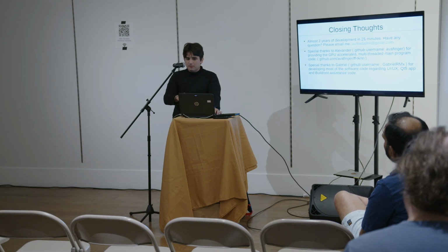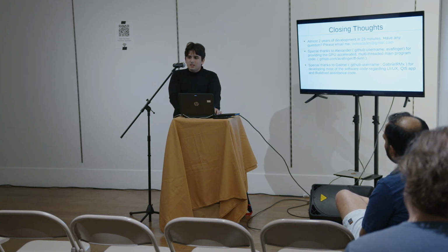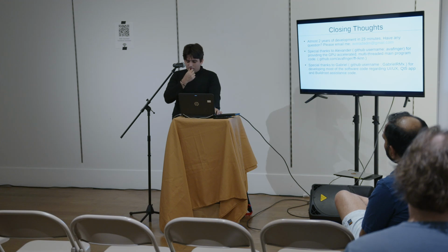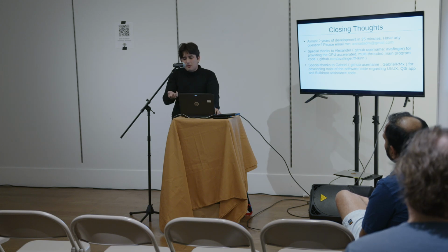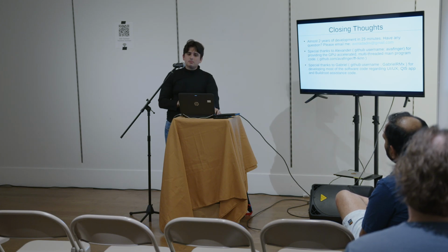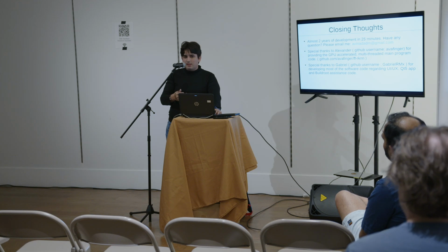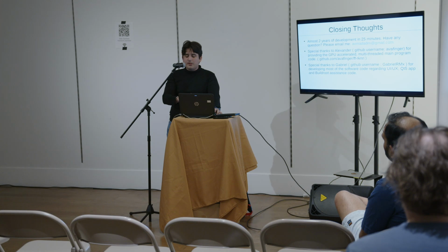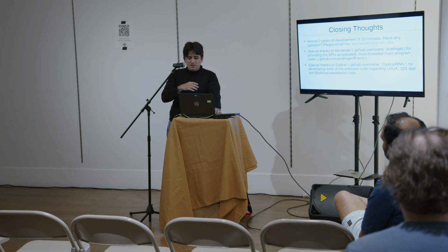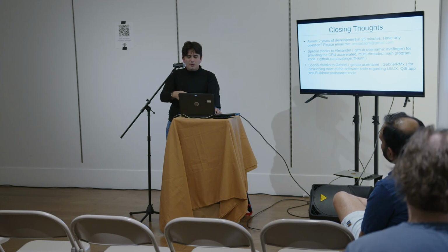Building the Buildroot image, I think it took us about... Well, the thing is that we probably had a working Buildroot image in 2 or 3 weeks, but as we were going along, we realized we were missing some very important features. For example, the camera engine calibration, which makes the 3A algorithm work, or for example, the GPU acceleration. So these were things we realized as we went.